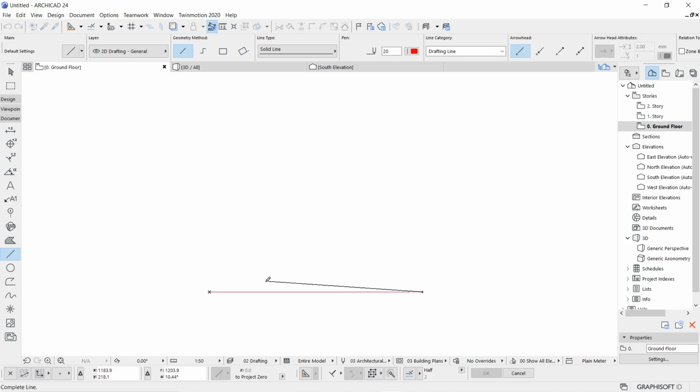Say for example, if I keep my mouse somewhere on the line segment, you can see that the same pencil icon carries a line inside it. So instead of a hollow pencil, now it comes as a semi-filled pencil. That is nearer, not exactly on the end point or midpoint. If it is a filled one, it is exactly the end point or midpoint, a genuine location. This is something known as an intelligent cursor. That is, the cursor can identify your location and according to that, it will give you some clue related to your precise drafting.